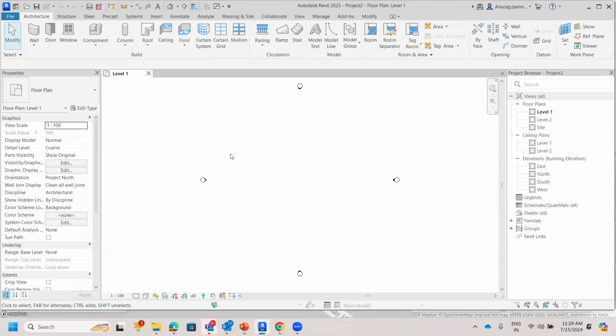So now we will be starting with how to acquire the coordinates and establish our own coordinates to start a project with a site plan if we have, or a survey plan if we have. So the first thing is to link a CAD file through which we are going to generate a toposolid out of it with the same contours, with the same levelings and so on.